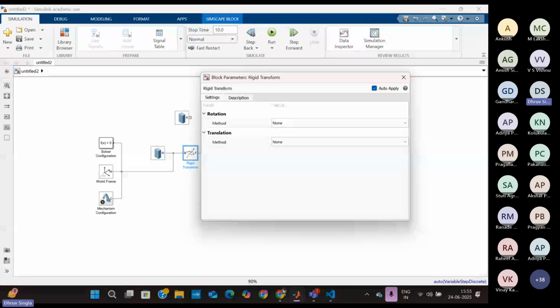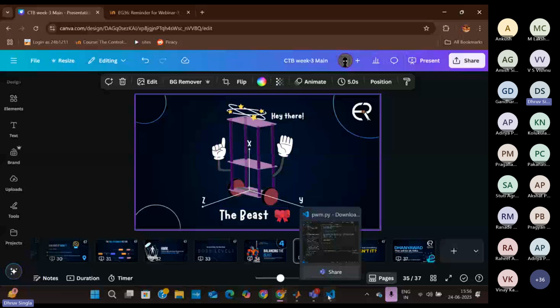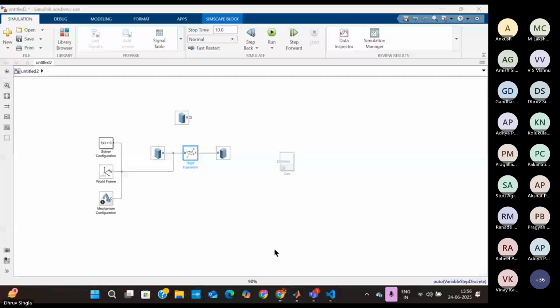Between the bottom plates, we want our length to be less. So between these two plates, we have our length in the direction to be 10 centimeters, and between the upper two plates, we are going to assign the distance as 25 centimeters. We have this unequal distribution so that we can keep the center of mass of our boat at a lower position, and it will help the stability of the boat as well.